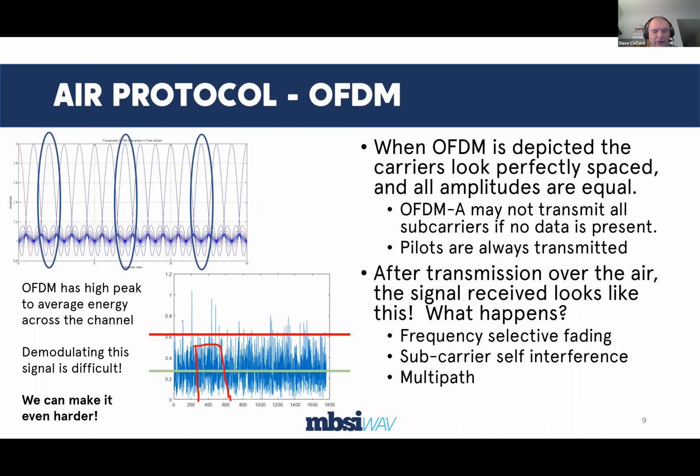The receiver in an OFDM system generally doesn't care about all the rest of this. Doesn't make any hill of beans difference. It's only concerned with the carriers that it needs to receive in order to pass its traffic. So that saves our bacon when it comes to the downlink. In the downlink, we can set the transmit power to achieve the range that we want, and away we go. Our issue here is strictly in the uplink.